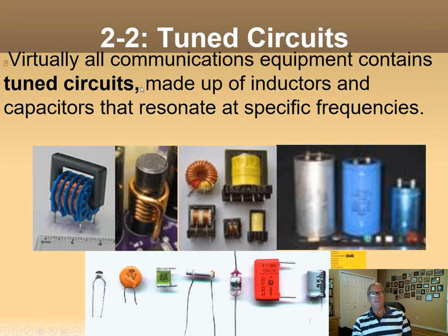So here's tuned circuits, our second topic. Here's some big capacitors, some smaller capacitors, all down here. There's ceramic. These are all leaded devices. A lot of times we use non-leaded devices now, surface mount, which have less inductance. These are coils of some sort, transformers, a toroid right there.